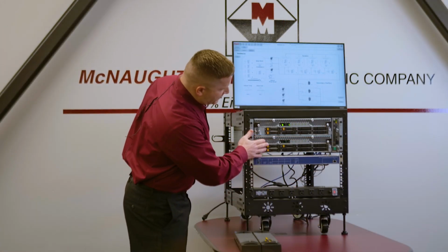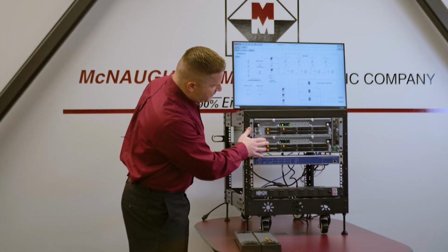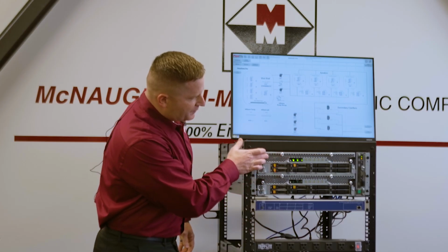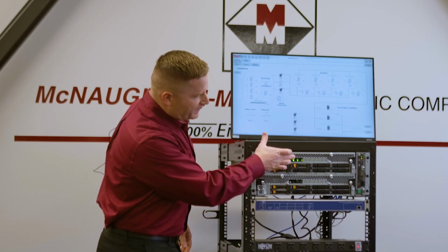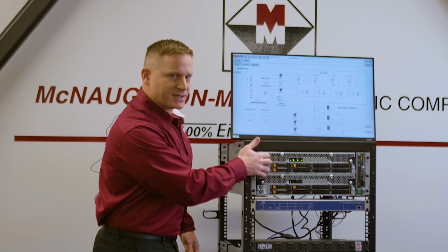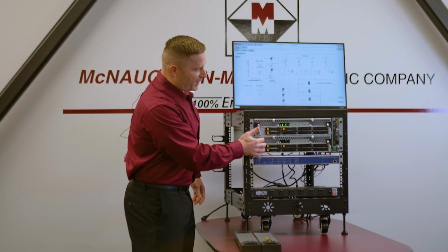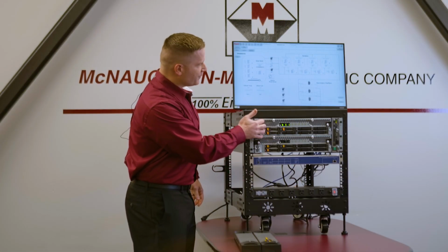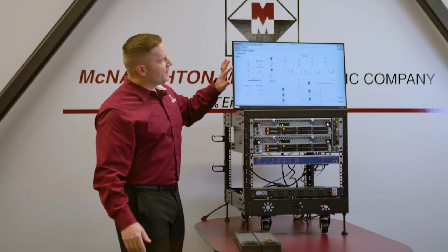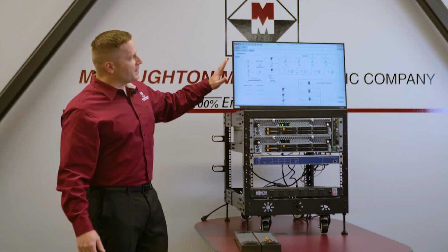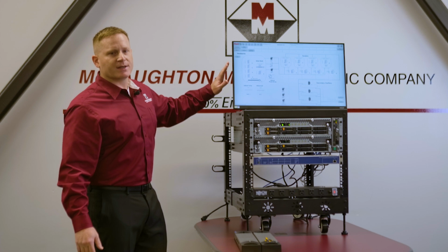And the bottom CRU has no indication lights that it's in operation. And on the top CRU, the safe to pull blinking light is saying it's running in simplex mode. So now we have a bottom CRU failure and the top CRU is still in operation and our PlantPAX image is still running without any pause.